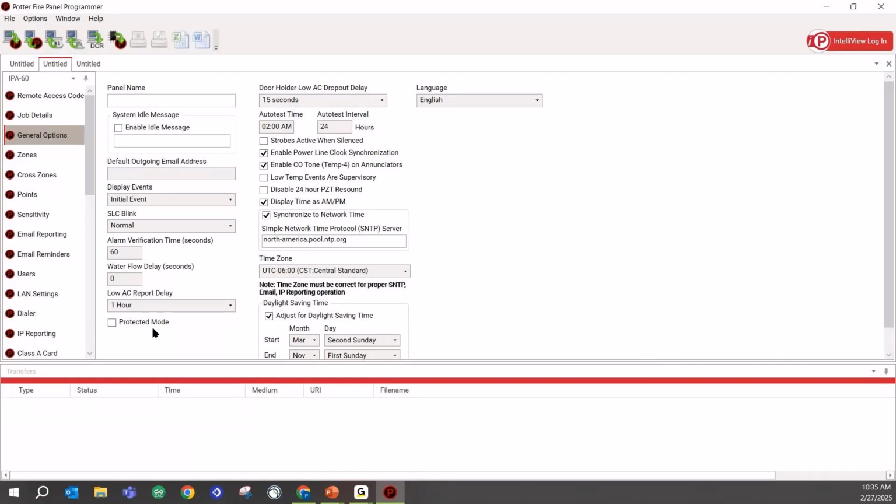So please keep in mind there is no difference between a smoke detector or a module for an AFC panel or an IPA. They're all going to be those PAD detectors. Anybody can go to ADI, SES, Alarm Max, etc., and purchase one of those detectors. So kind of the way I like to lean into this is, let's say you tell a customer that it's going to be $300 to replace the smoke detector, just to make up a number. It seems like a lot of customers have, I've got a cousin who can do that for $75. Okay, fine. Well, they can go down to ADI and they can buy that detector. They'll take the old one down. They'll match the dip switches, put the new one up.